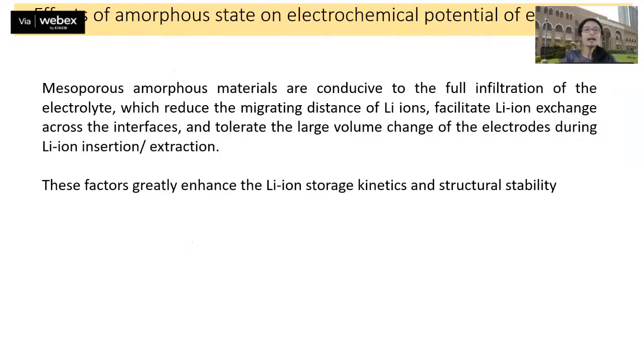So basically, this is kind of an antagonistic thing, that you need porous material to improve the storage kinetics and structural stability, but at the same time, you do not need that many pores, so that it does not give a disadvantage by forming a very huge amount of SEI, leading to the loss of lithium. So you have to strike a balance between the two, and that is what generally researchers do when they are finding out new electrode materials in the lab.